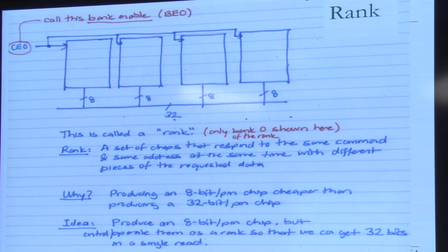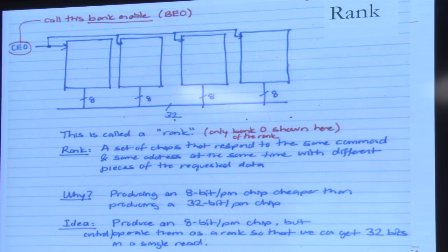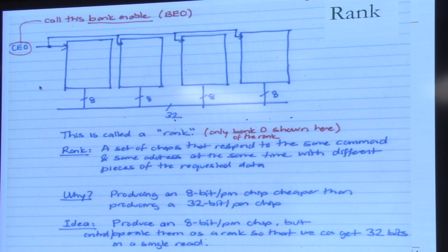That's true for the processors as well, actually. Adding more channels is much more difficult today because it requires more data pins, right? That's why memory bandwidth is not scaling as well. Otherwise, you would add many channels on a chip, right? And also think about another way. Eventually you become area limited, right?